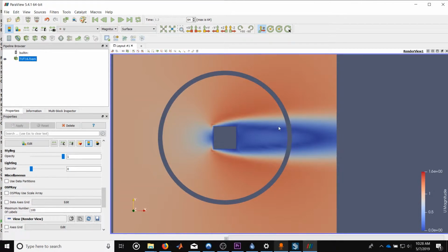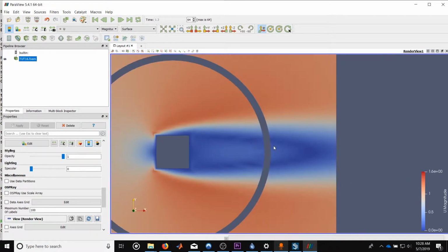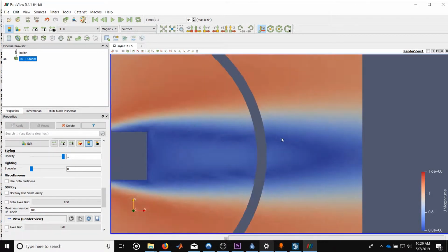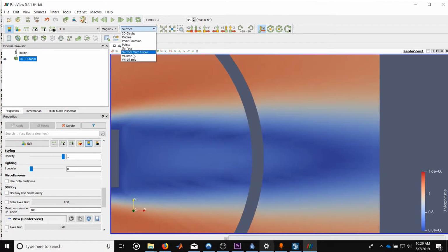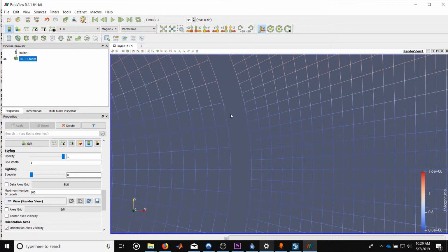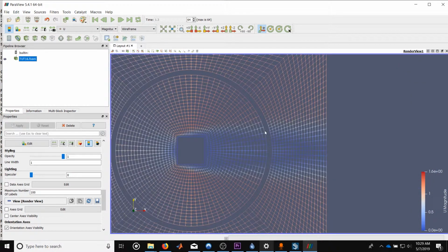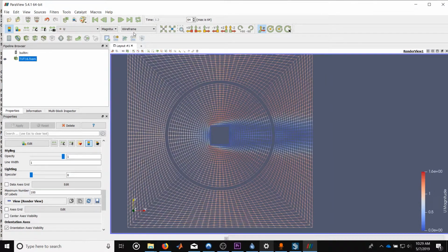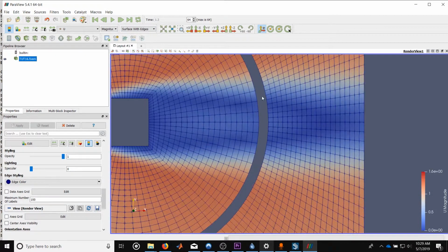That's because the cyclic AMI allows these faces to talk to one another. The patch weights are calculated once at the beginning of the program, and then this face is talking to that face, this face is talking to these three faces, this face is talking to these two faces. It's recalculated each time. That's what's important about the cyclic AMI. It allows different faces to talk to one another even as they move.